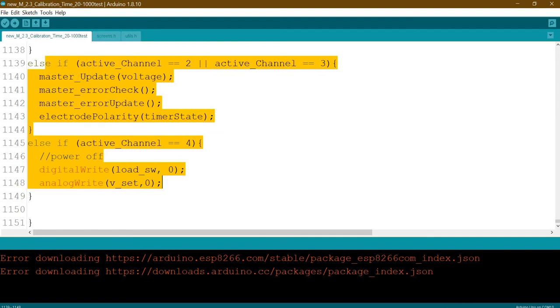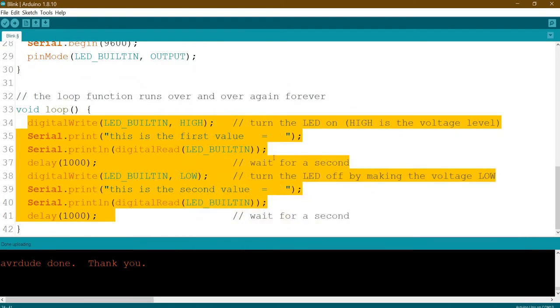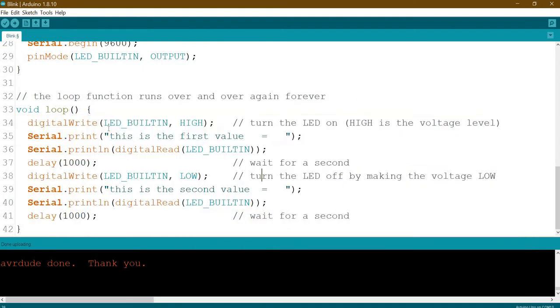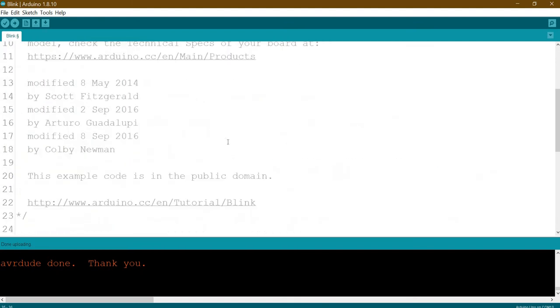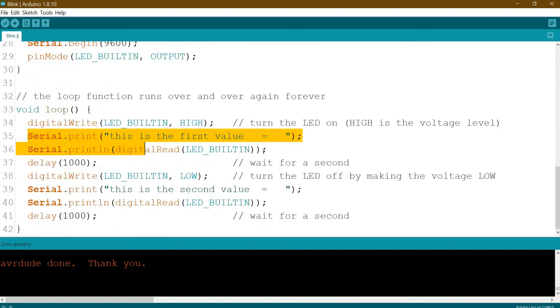You will use a lot of serial monitors here and there. And by the way, all these serial prints will delay your code and take space in your code also. Why?